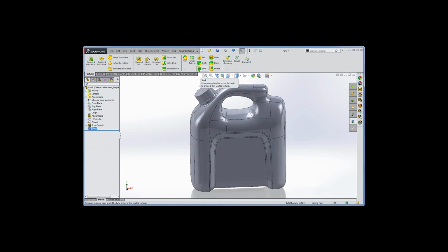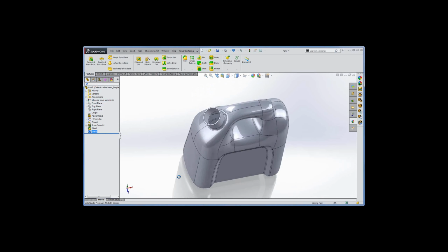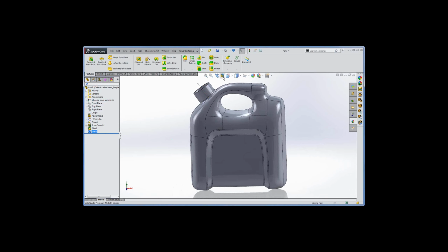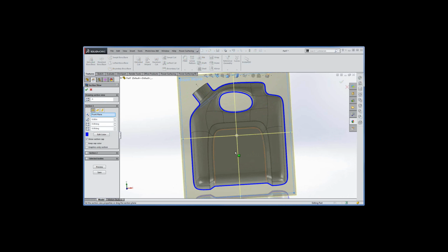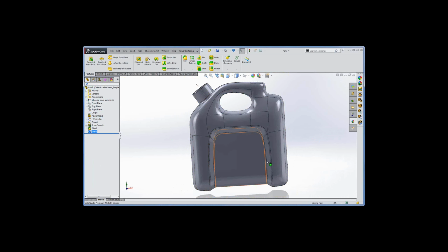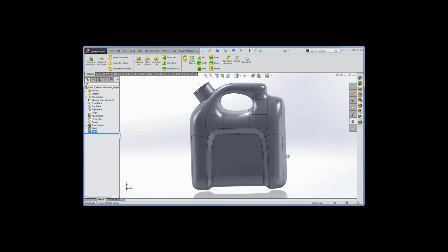And then, of course, one of my other favorite things, fillet being my favorite, is shell. So we'll go ahead and shell it. Just use the default. That should be fine. So give you a section look at it, show you that it's nicely shelled. And so there we have it. And then you could do some extra stuff. Well, except for one thing.